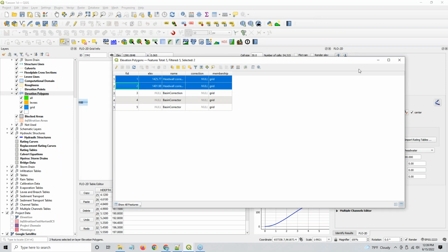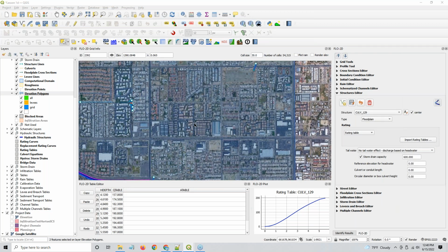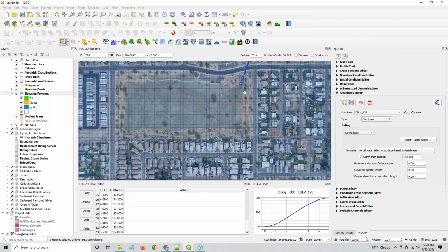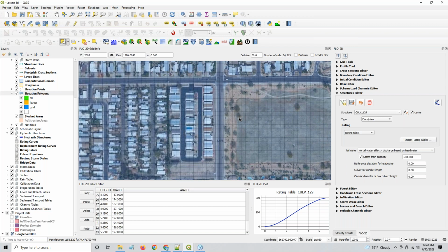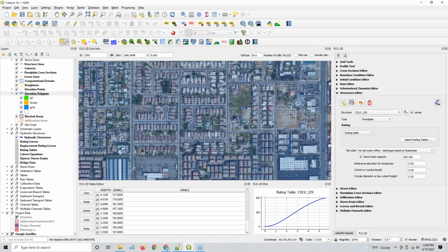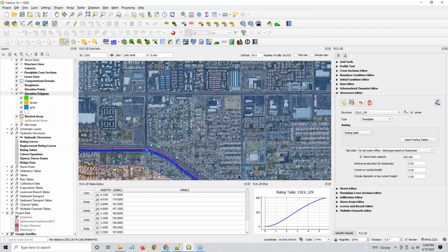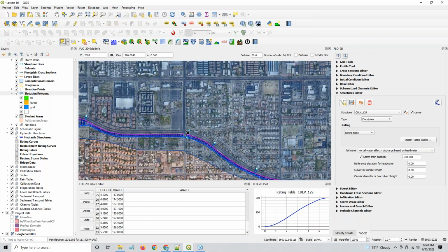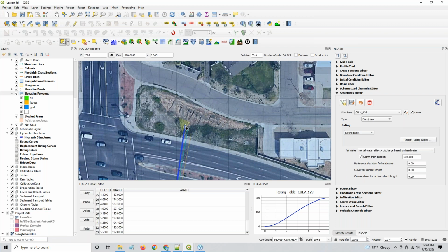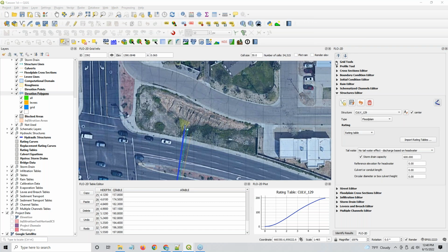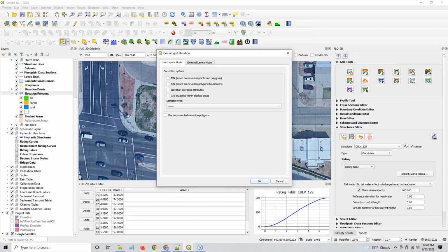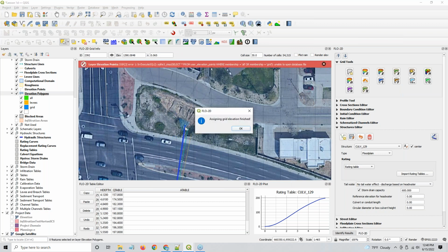So look, if you look at these, sorry about that. I apologize for that, but there's one here called a head wall correction, and there's another one somewhere else. I think it's in that other basin that was right next to the channel. Yeah, there was another one right here. So we're going to apply that correction now. I've selected those two, and this one's a lot easier. You go to grid, you go to this guy, and this time we want elevation polygon attributes, only selected features. So then that will reset those elevations.